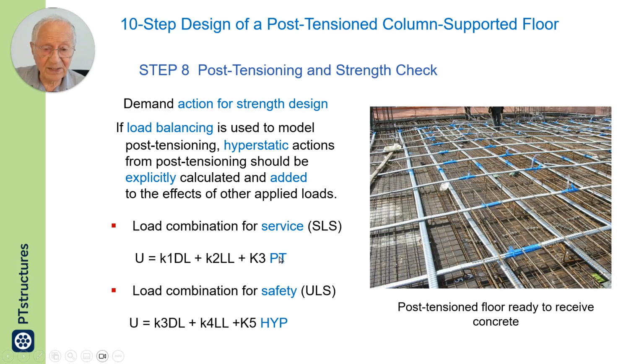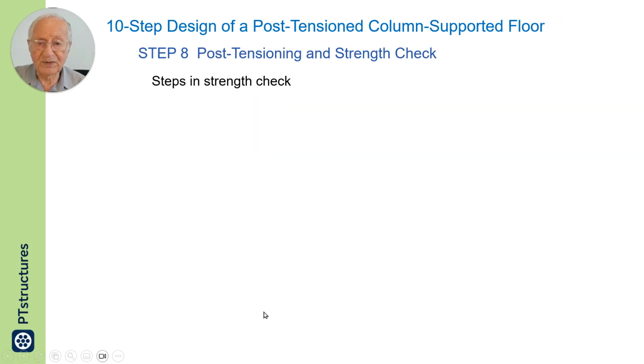But for post-tensioning, the magnitude changes and the coefficient changes. So the objective of repeating the load combination is to emphasize that the magnitude of the quantity changes in the two, and obviously the coefficient. So we have to calculate the hyperstatic actions from post-tensioning.